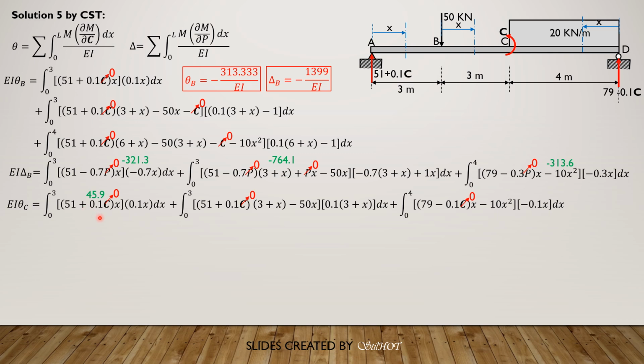So the first is similar to the expression from virtual work, 45.9. Second term, 208.8, similar also. This is the new term, but we expect the same result of negative 1568 over 15. So combining, theta C is 150.167 over EI, just like before. Then finally, we remove the loads and the reactions and replace them with an upward force at C. Then this will be the result. Due to P, the reaction here is downward, so it's negative.